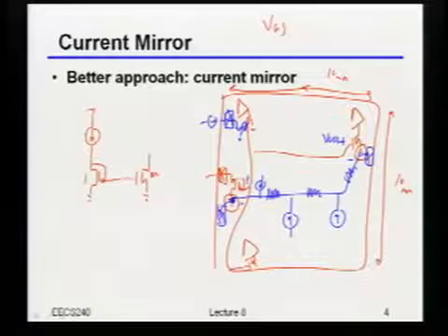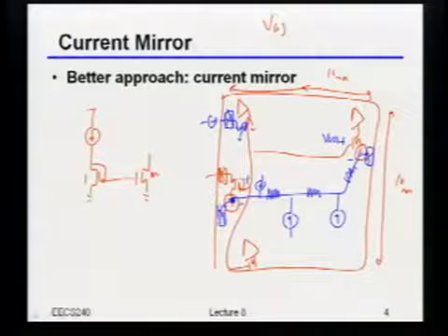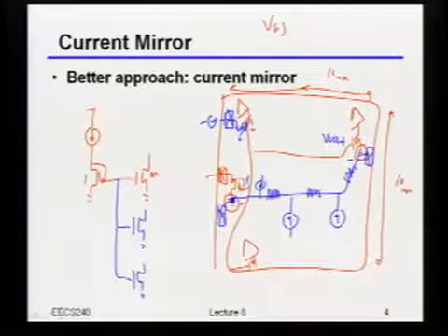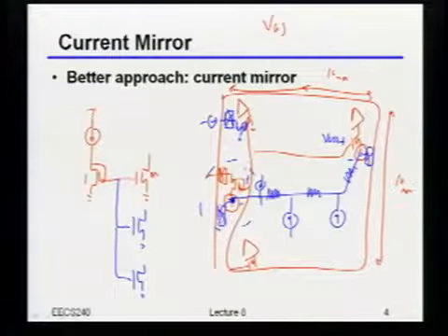If I had a chip with 100 or 1,000 or even 10,000 amplifiers, I probably don't want 1,000 pads for external bias currents. So I want to find a way to do almost the equivalent of what you're saying. How would I do that? Distributed current. Yeah, what I really want to do is distribute the currents. So if I had 3 different places I need to go to, locally, at the point over here where I got the bias current in, I would mirror this over to 3 different mirror legs.